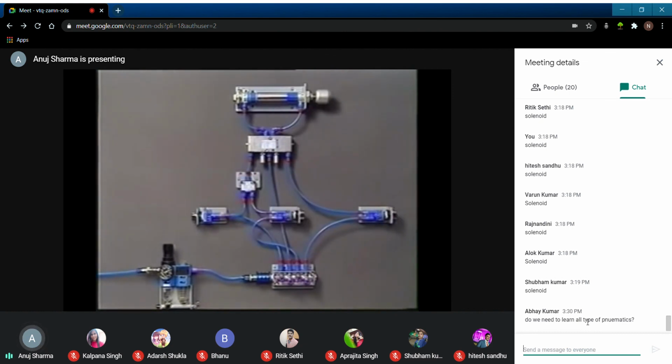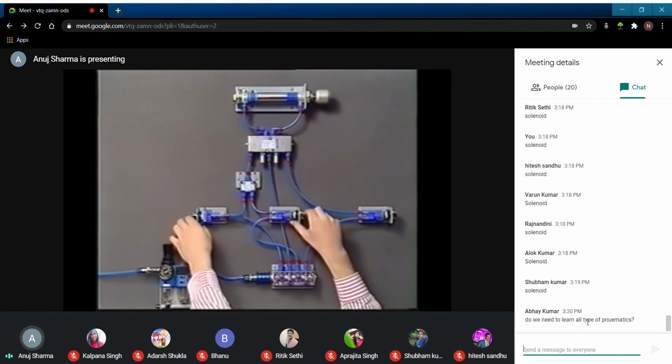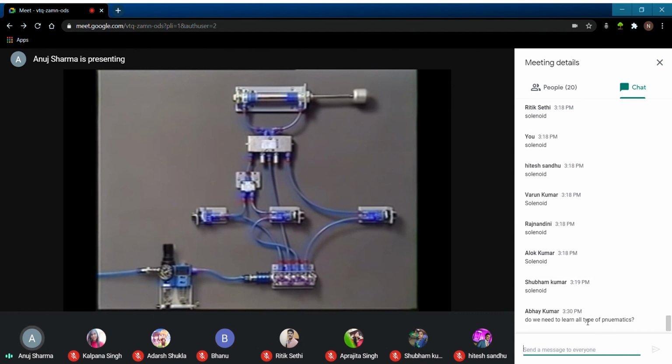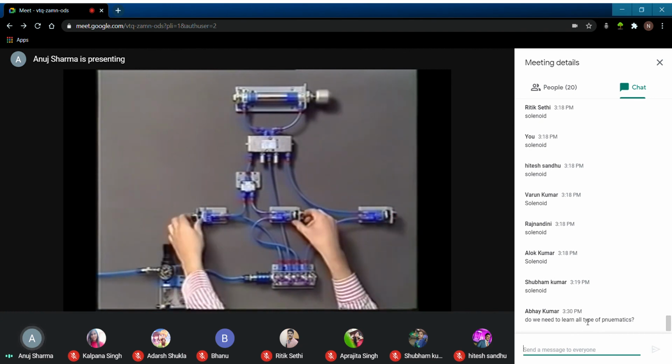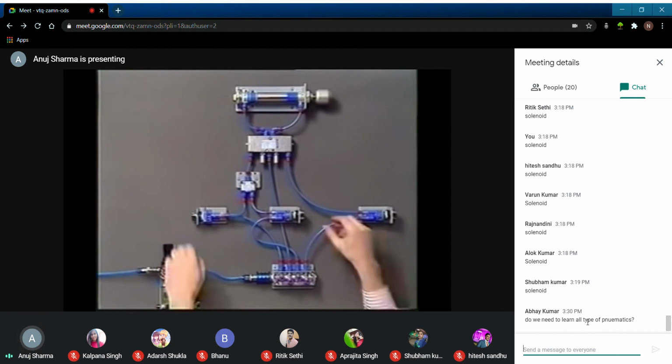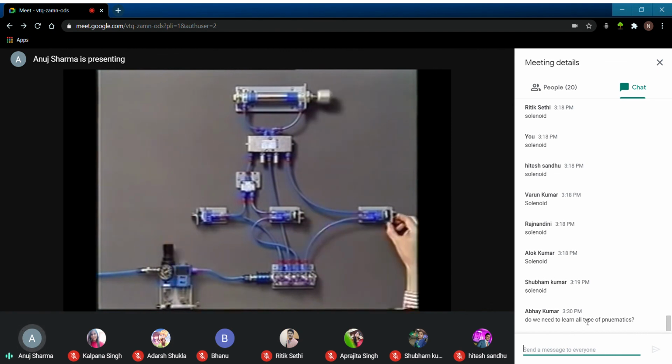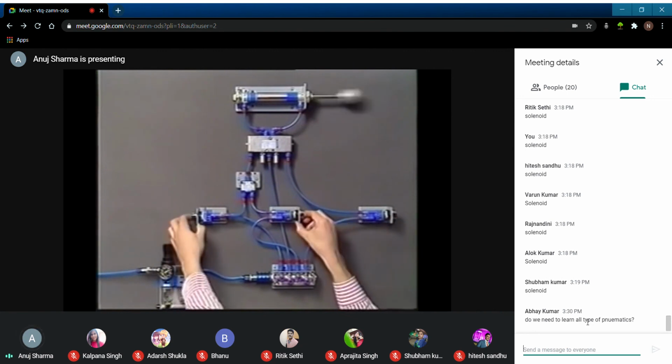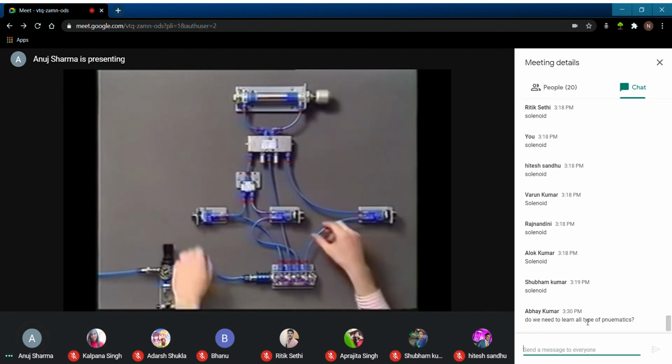Another consideration is to incorporate safety features into the control system. For example, a second push-button valve was added to the extend side of this circuit. This design requires that the operator use both hands, pressing both push buttons at the same time to extend the cylinder. An AND valve is included in the circuit to provide this function. In order for the cylinder to retract, the third push button must be pressed.